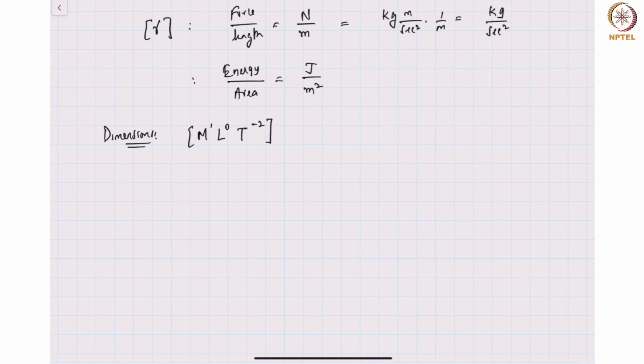Now we will look at the surface tension of some common liquids. For example, the two common ones I'll tell you are air and water. Surface tension is around 0.072 Newton per meter, and therefore this can also be written as 72 millinewton per meter. That's the value of surface tension for air-water. But whenever you have air and water, there's an important convention.